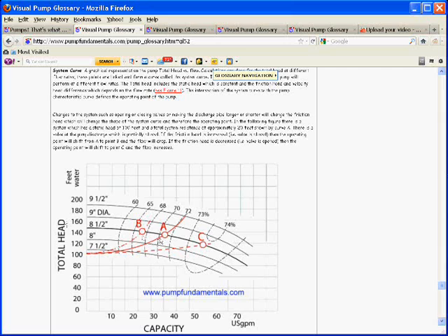So as I close the valve, I have additional friction, the flow will drop. So you see I would go up on this curve here and wind up somewhere here with less flow, higher head. And the same thing would happen if I open the valve. Then I will have removed a lot of the friction, therefore the flow will increase. So I will need less head, but I'll have higher flow.